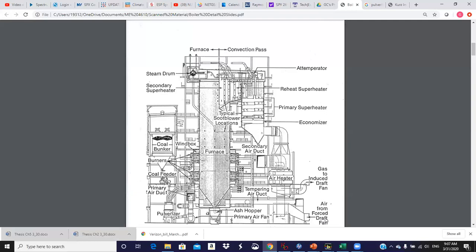And so if we pull this forced draft air from that, we're recovering some of that heat that was lost from the shell of the boiler, and we can put it back in the furnace. So that's where the air is pulled from. You want the warmest air possible because that's going to improve your efficiency a little bit. So we're going to pull off of the top of the boiler house.